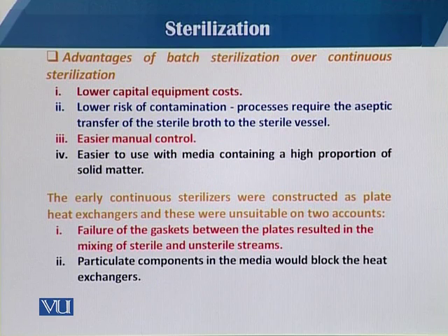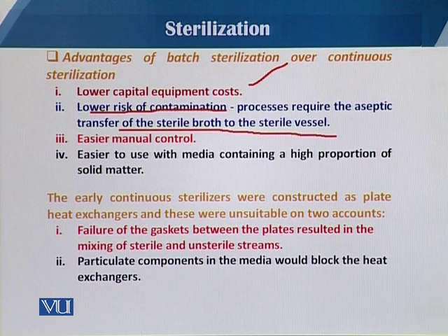As concerned the advantages of batch sterilization over continuous sterilization, it requires low capital investment and has a low risk of contamination, because in continuous culture we need sump and dump lines.